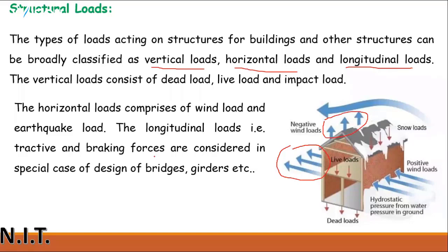Longitudinal loads are applied in bridges and girders. The vertical load consists of dead load, live load and impact load. Horizontal loads comprise wind load and earthquake load. Longitudinal loads are usually the tractive and braking forces, considered in special cases of design of bridges and girders.